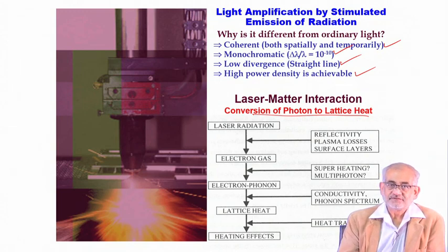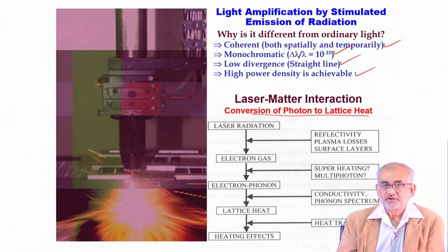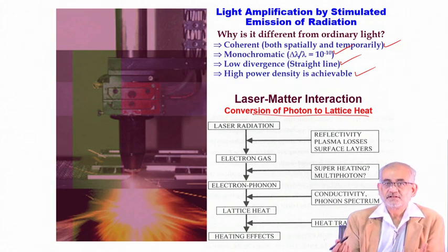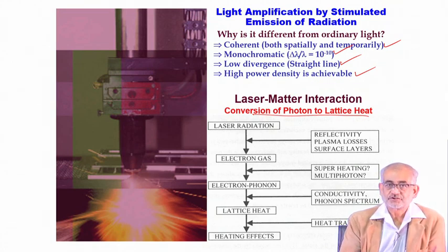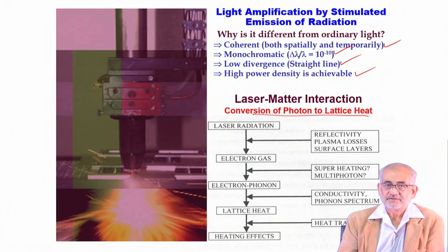On the other hand, if you are dealing with a semiconductor or oxides or ceramics or compounds, or even covalently bonded polymers and so on, then coupling is much easier. One way of overcoming this problem would be to raise the temperature, where the coupling efficiency increases, or to go for lower wavelength lasers, so that the coupling efficiency increases. For that reason, you would prefer Nd-YAG laser or solid state laser, or for even shorter wavelength one goes to excimer lasers or diode lasers and so on and so forth.